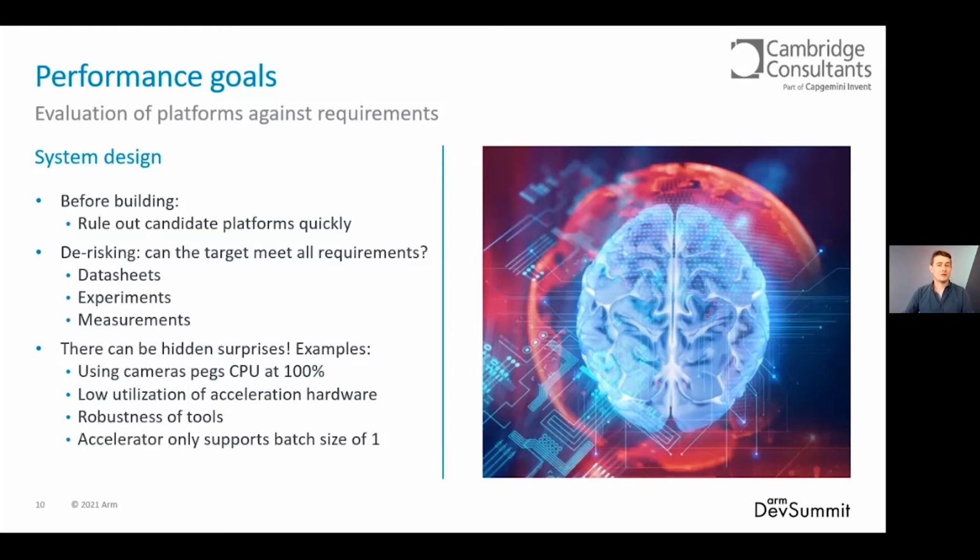Running experiments with the device is often important for Edge AI. Lots of devices and tools are still in active development, and surprises can pop up from time to time. These may only be discovered by experimenting. Alongside this, datasheets and marketing materials may only give headline figures for the device. The actual performance with the target neural network can be a long way off these. Because power consumption is a complex function of what activity is happening on the device, it is valuable to measure this on the bench. Datasheets, again, will often just give nominal values for power consumption.